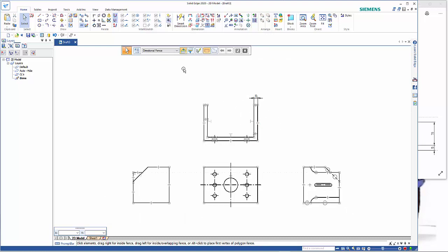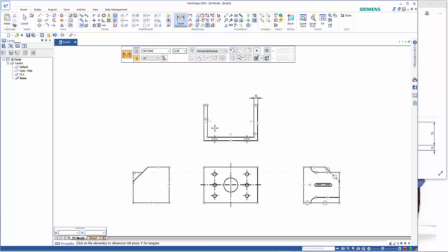And what I'd like to do also is just increase that to twice the normal size. So from here we're looking at placing some dimensions. So smart dimensions, still on 2. I can come in here, 150. That's 40, radius 4, radius 15, that's 100, that's 100. And as you can see, we drew it all to size.